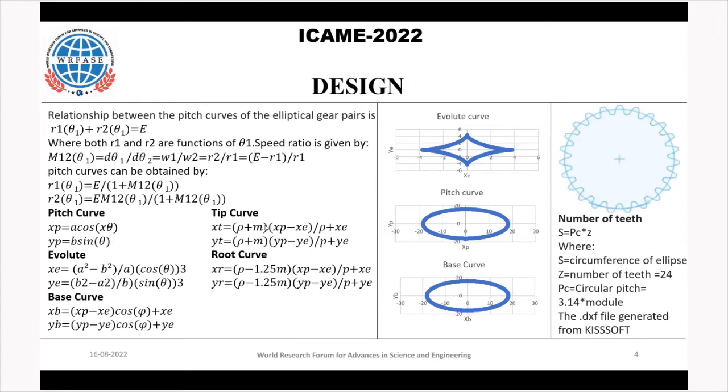The methodology used was that the non-circular pitch curve is divided into several circular arcs with different radii of curvature and centers of rotation, and then generating the teeth as a sequence of connected parts of several circular gears, where each tooth of the resulting non-circular gear corresponds to a tooth of a circular gear with the same radius of curvature, module, and standard pressure angle. And correspondingly, each part of the rack was also designed for the respective circular gear.